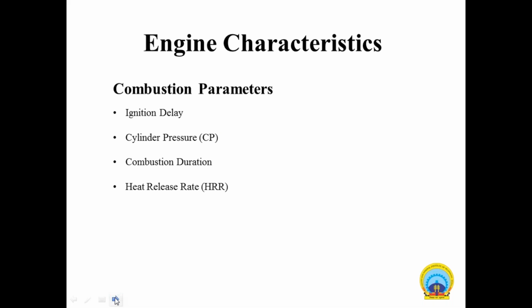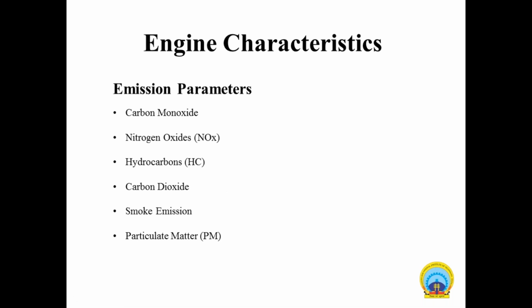So in the emission parameters, change the slide. In the emission parameters, there are mainly 5 or 6 parameters: carbon monoxide, nitrogen oxide NOx, HC hydrocarbon, smoke emission, then PM emission, that is our particulate matter.